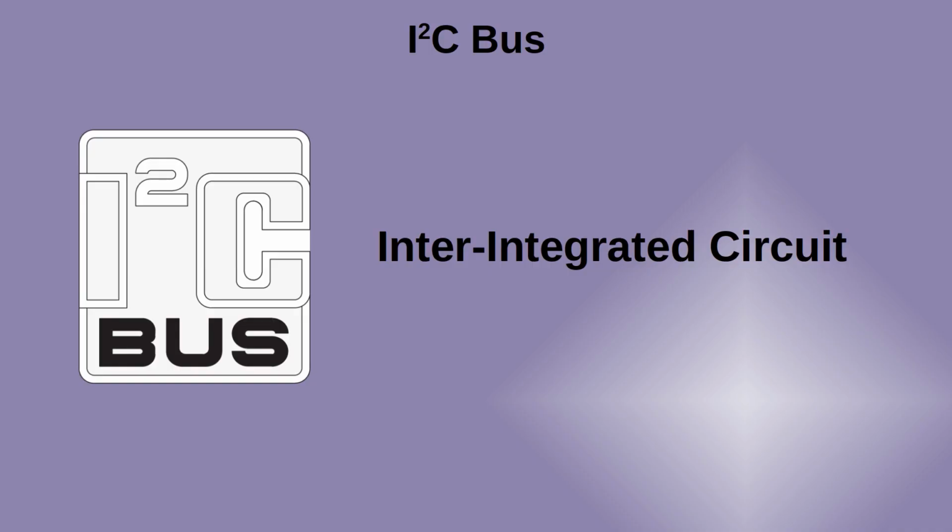I'm going to start by looking at I2C and how it can be used for communicating between devices. I2C is an abbreviation of Inter-Integrated Circuit. You'll also see it written and referred to as I2C. This is particularly popular in code examples or online where creating the superscript for the 2 is not so convenient. It was created by Philips Semiconductor as a way to communicate between integrated circuits needing minimal connections. It is a common protocol often used for connecting devices to a computer or a microcontroller.